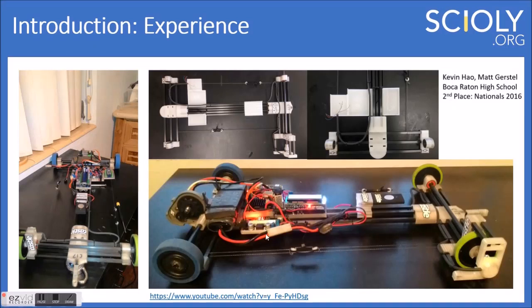We have a voltage regulator that you can see down here, and that was just feeding the motor a consistent voltage, as well as powering any other electronics that we needed at a certain voltage. I don't remember exactly what we were using it for. I think the motor was run purely off the 7.2 nickel metal hydride battery that we have under this steel block over here. And I think this voltage regulator was to ensure that when the voltage dropped, because the motor was pulling so much current, the electronics on board wouldn't turn off. It would boost up the voltage if it was dropping, so that the Arduinos were getting fed a constant voltage, which was very important to make sure that they did not just turn on and off. We did have that problem a little bit.